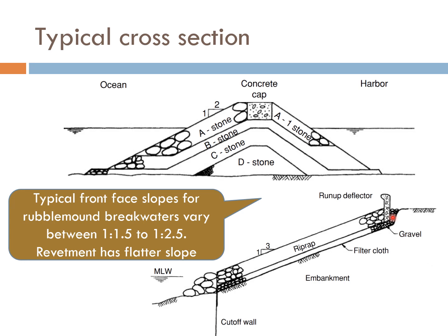Most breakwaters which are constructed onshore will also be used in conjunction with geotextile to prevent the scouring and loss of the finer sand material from the beach.